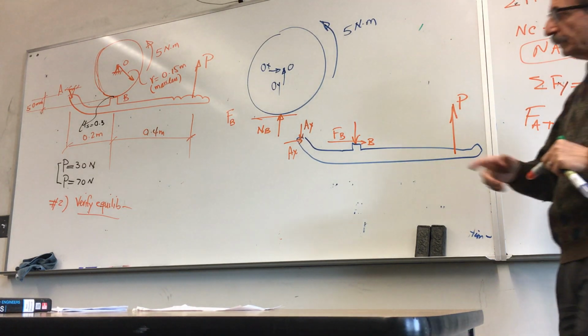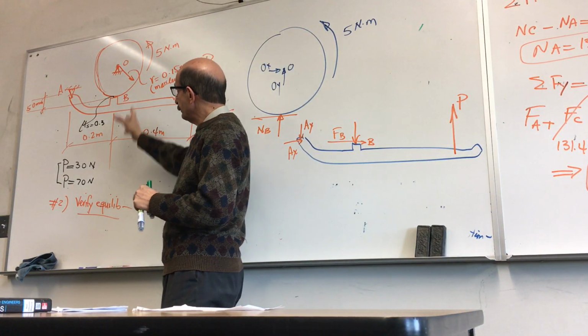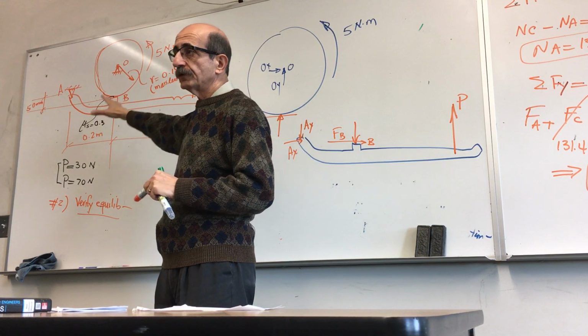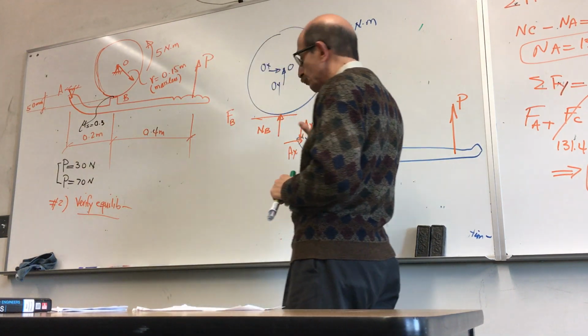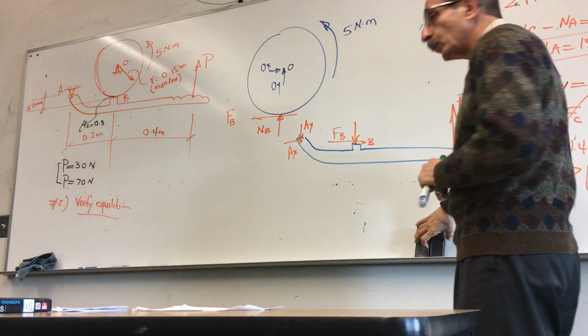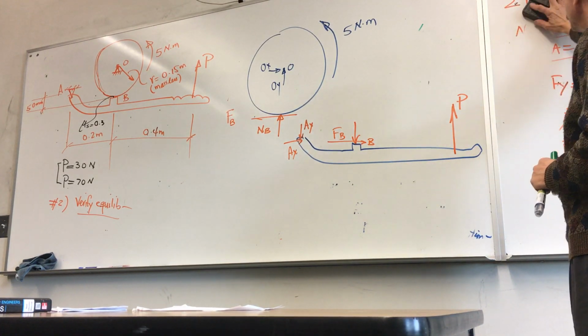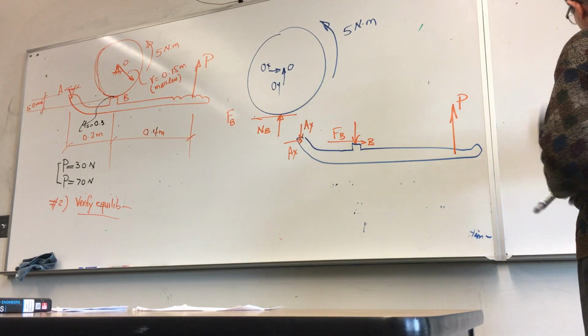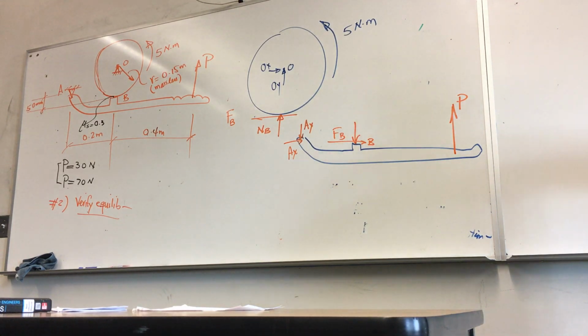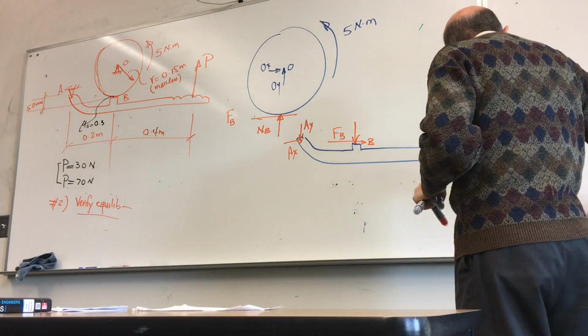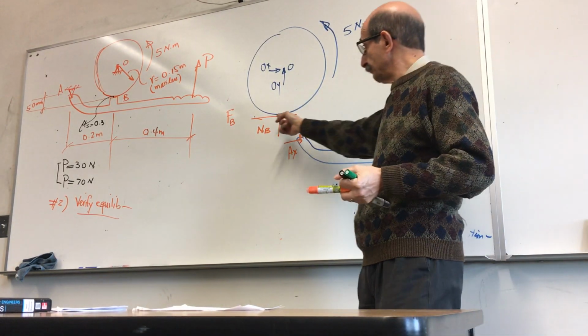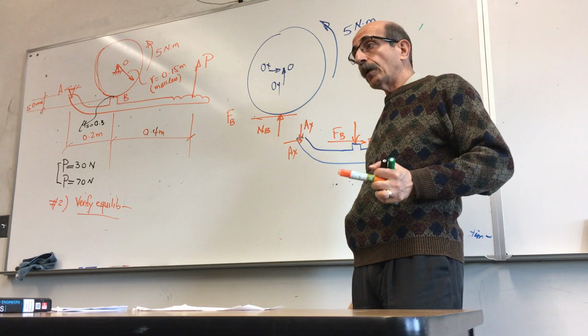As a step 1, we decided which case it is. As a step 2, we drew the free body diagram with the understanding of what potential direction the motion may occur, so we can identify the direction of the friction force properly.